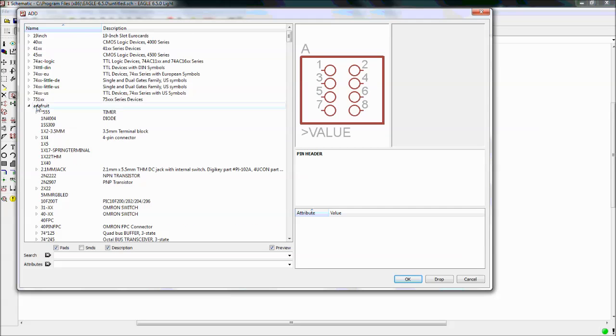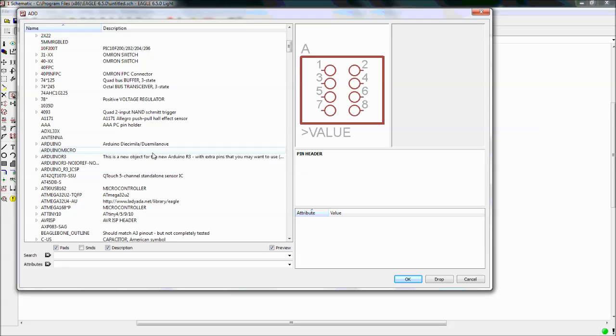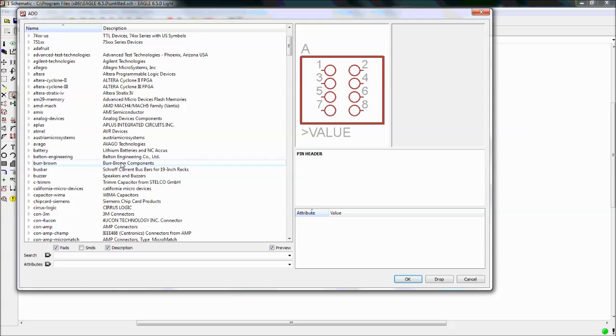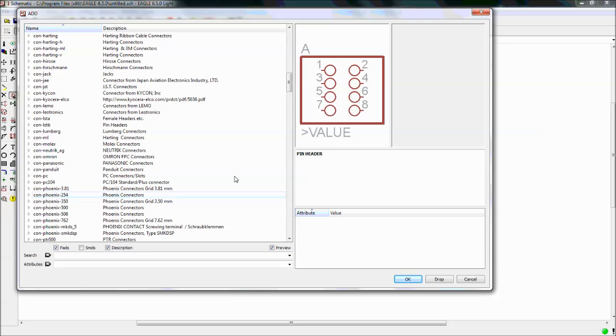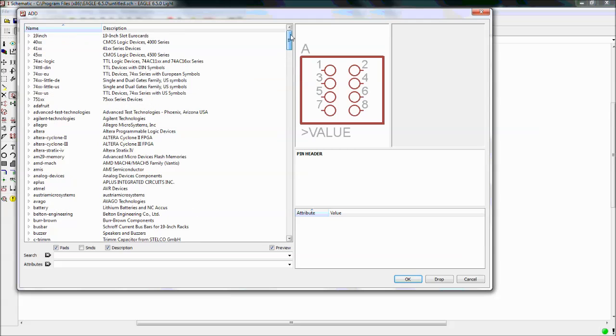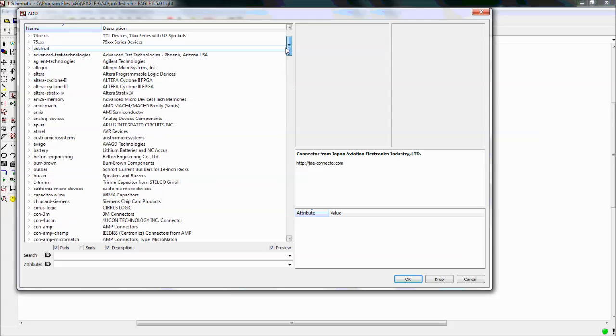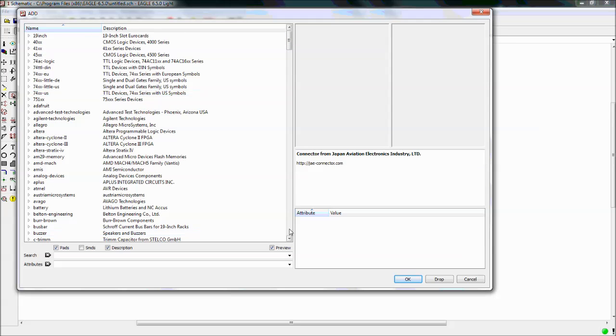So I will recommend you to download this Adafruit, as well as one more file. Search it on Google: SparkFun Eagle libraries. You will get a lot of options in that. In the SparkFun library, all things are sorted out separately, like gas sensor, temperature sensor, regulator. You get them in a single library, but inside that library they are also divided properly, so that you can use many components from a single library itself. Because for a general engineering project, we don't need all libraries. That is important.